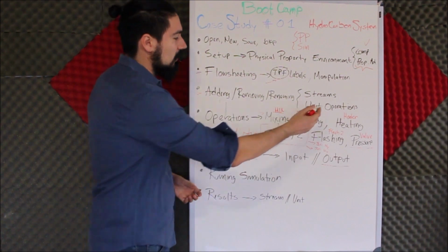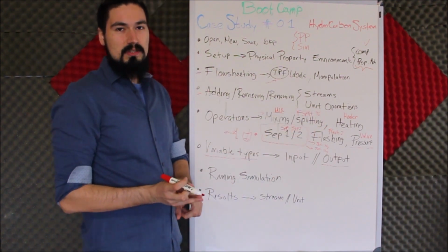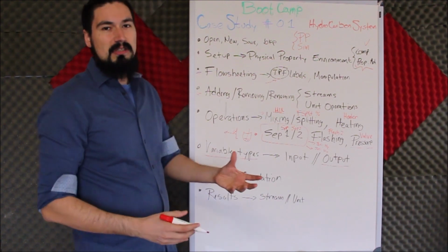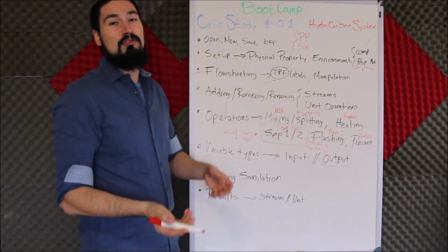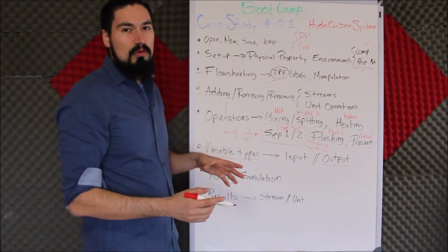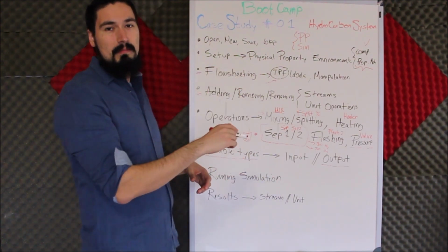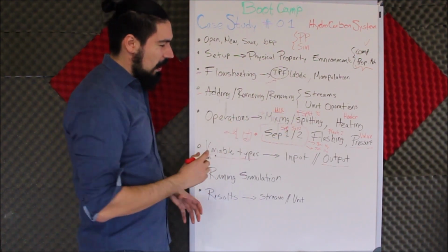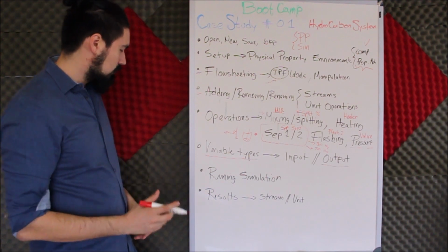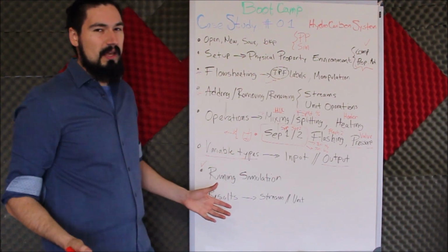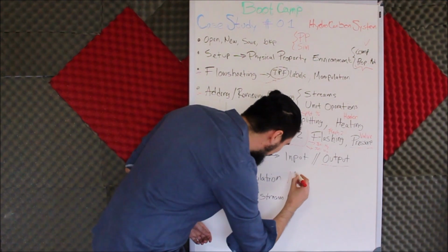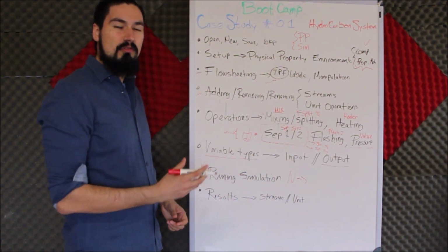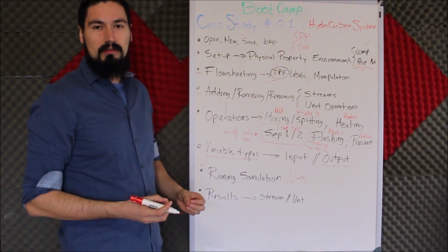For instance, if you're talking about a heater, you have a flow rate, which has a temperature, a pressure, and a duty. You will not be able to select the outlet temperature because you already have a duty. And the reverse is true. You have the outlet temperature, inlet temperature, you know the mixture. By definition, you can solve for the heat duty. So this is how we're going to treat input and output variables. We're going to see how to run the simulation, how to click the beautiful Next button, which will allow us to continue with the simulation in order to run with the least requirements in the simulation.